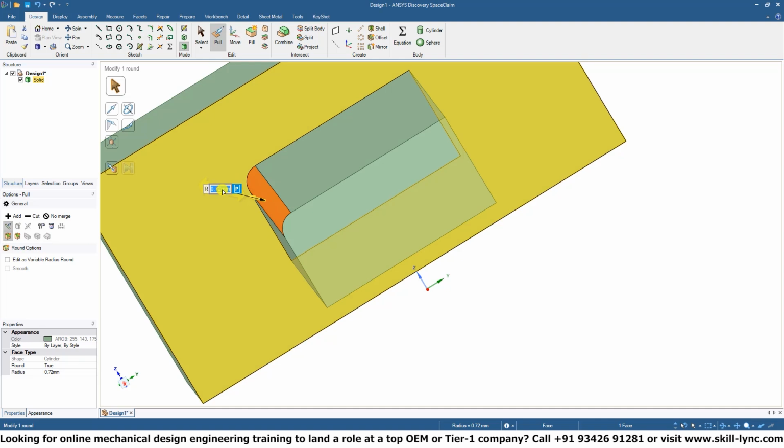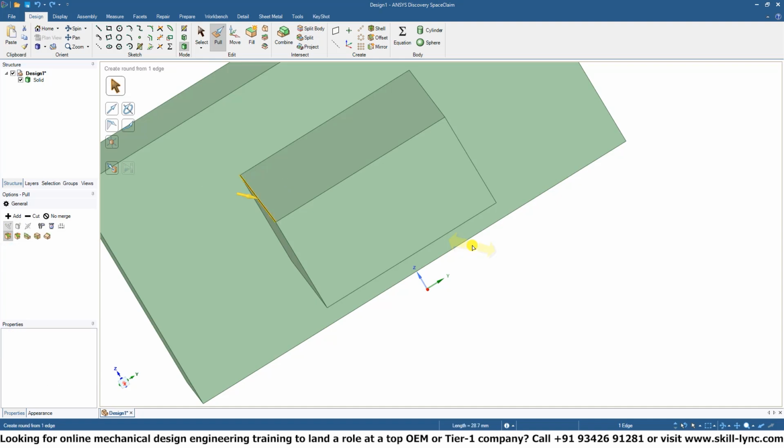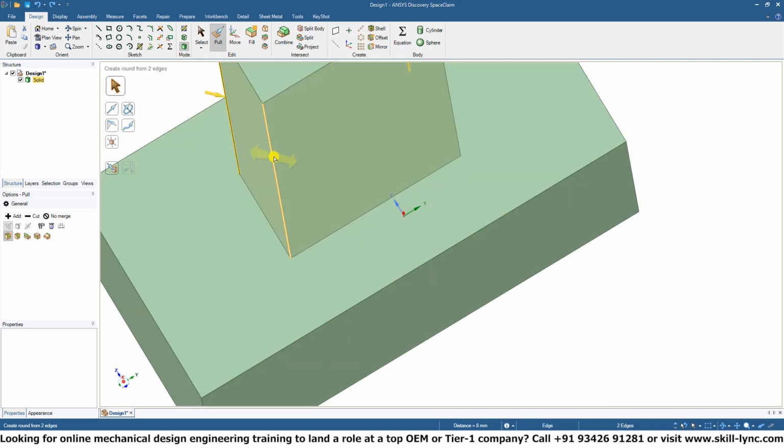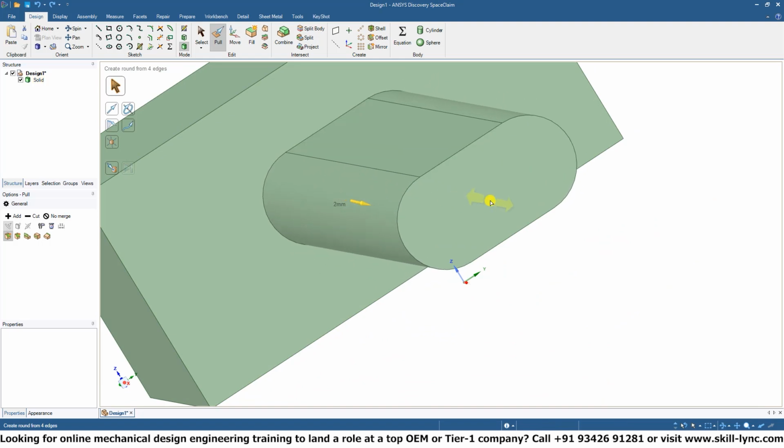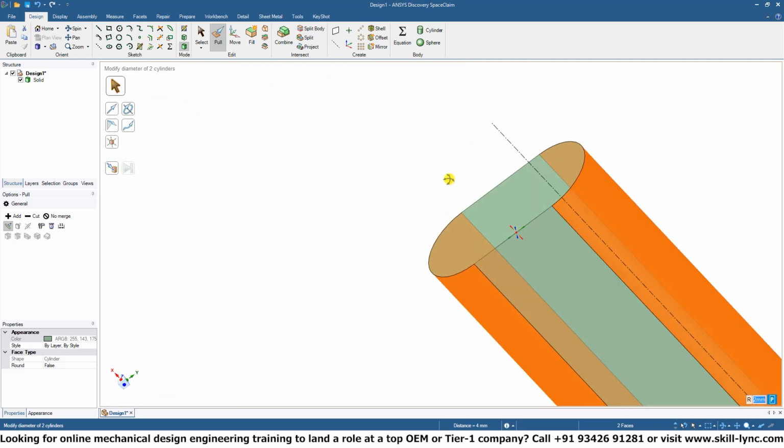You can also define the radius of the fillet that you want. Over here we have 0.72 millimeters, just done through clicking and dragging. If we set this to 2 millimeters, it automatically updates it. What we can also do, if I do a bit of Control Z, is select multiple edges to edit at the same time instead of editing solely one singular edge. And now if we drag, you can see how all 4 edges are edited at the same time.